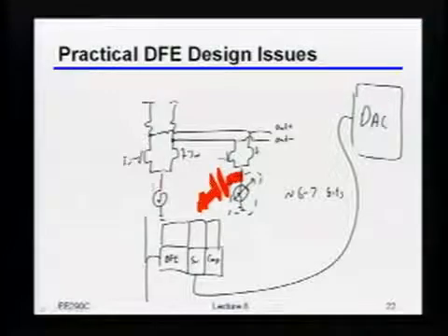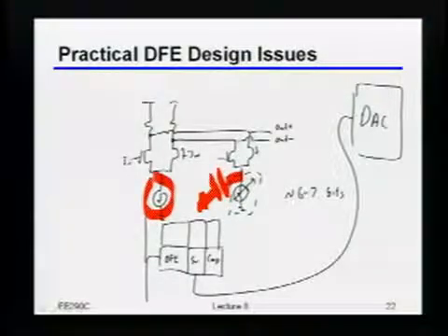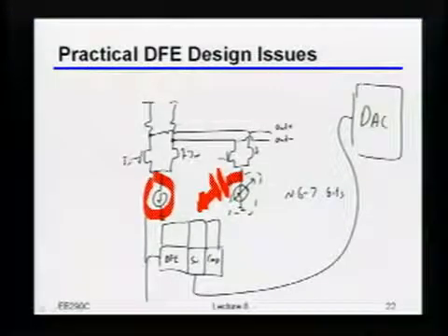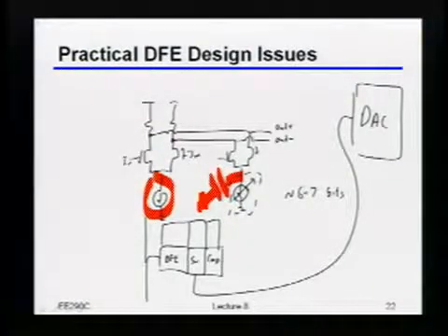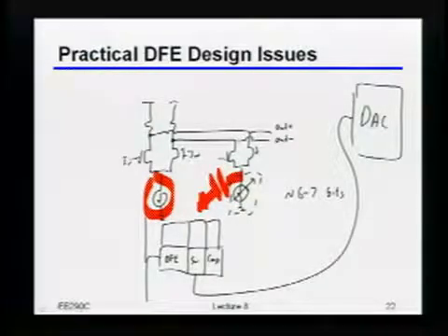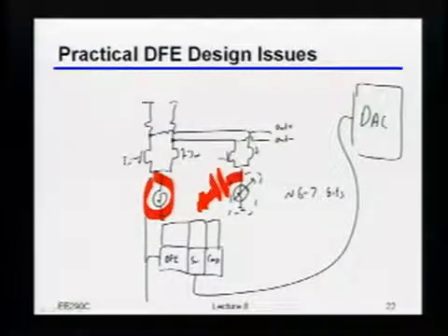In fact, even for this tail current source, if it ends up being big enough compared to your core high-speed devices, you may even throw that out of your high-speed path and just route that tail. It does mean you're giving up some differential noise, or rather common mode noise immunity. But if you're careful about it, that may be the more optimal solution from an overall power and feasibility standpoint.